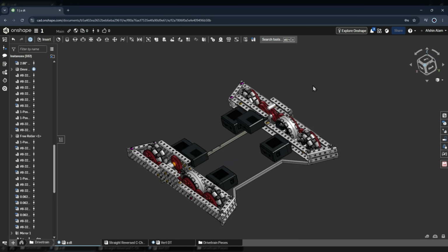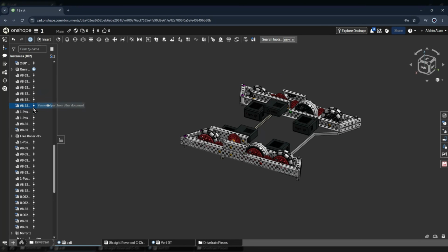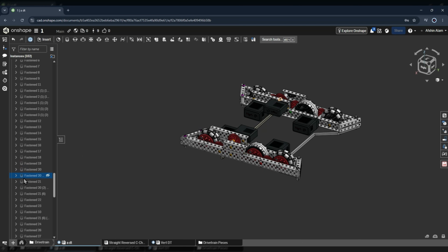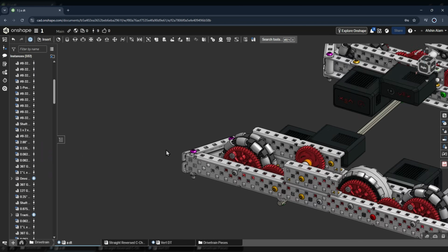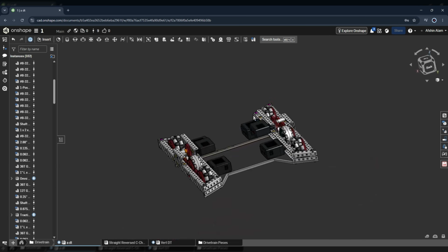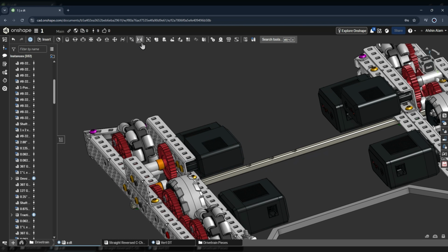But after that, now we're gonna look at basically decreasing the amount of things that are over here. The more functions and tools that you use over here, the more things, again, that this will have to load, and the slower that your CADs will be. So a few ways to decrease that is, one, using a group tool.